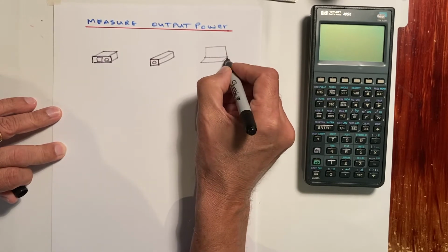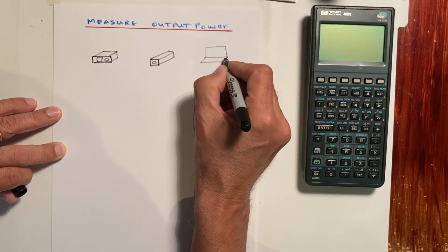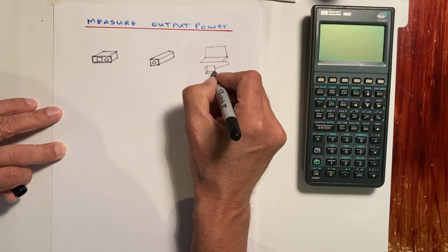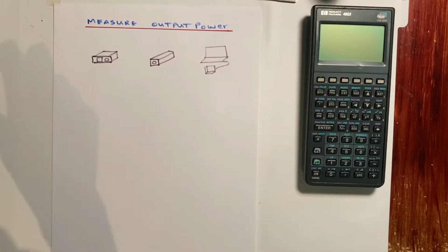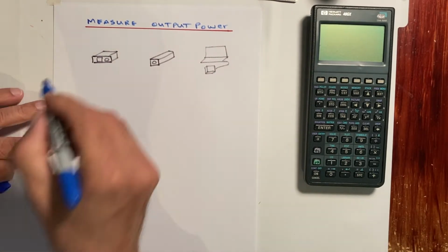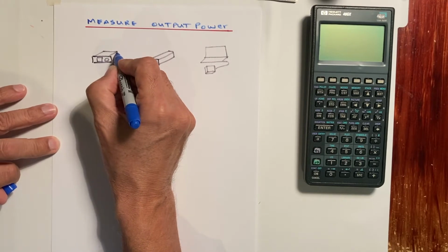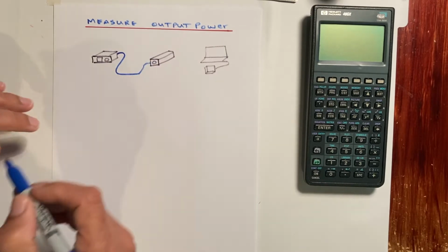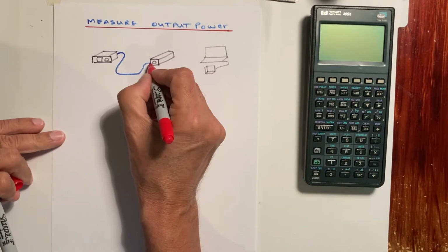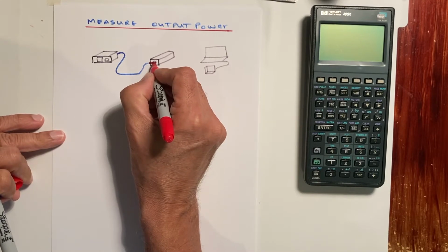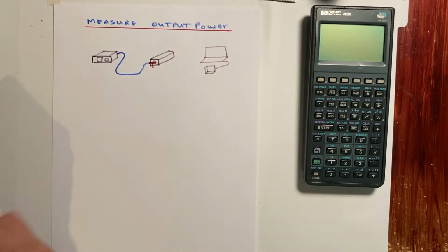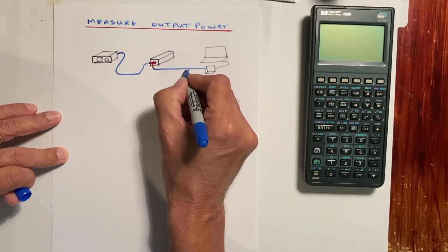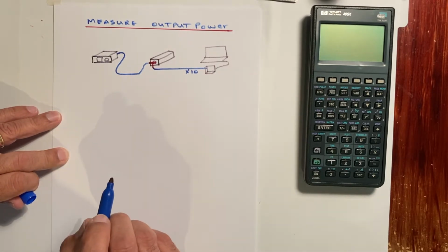It's actually the 2204 Picoscope. So this is connected via USB to a box, which is the guts of the oscilloscope, and it's going to have our measuring circuit. So out of this transceiver, we're going to have our antenna lead coming in this direction, and it's going to go up here to a T connection, and we're going to be coming out and going into the times 10 probe of the oscilloscope.